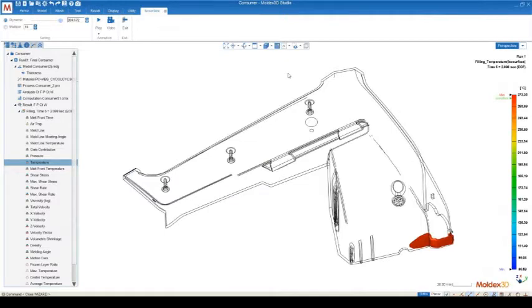And when we're talking about warpage, about analyzing the final part that comes out of the mold, the shrinkage variance across the part is where warpage originates from. And the temperature differences, especially in the thickness of the part, are going to play a huge factor in the shrinkage variance across the different regions of my part.